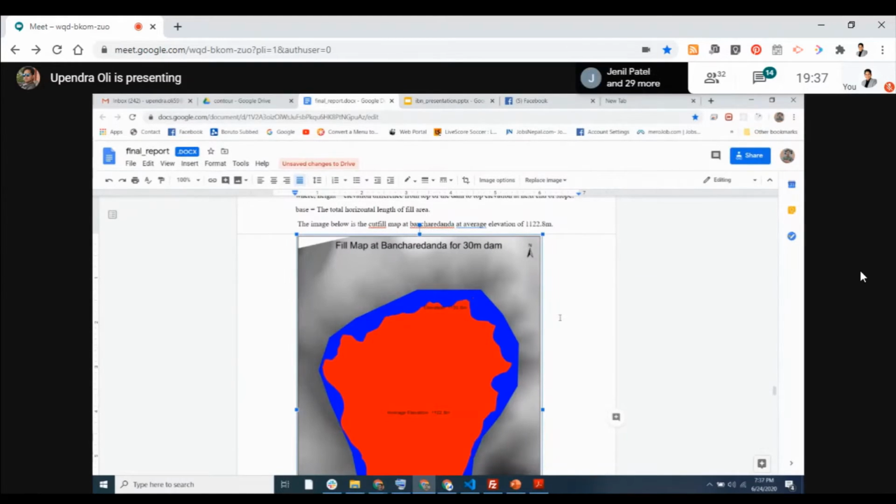But the volume calculated from Pix4D is from the DSM, the digital surface model, which includes the heights of the objects above the ground. That can be trees or grass or a house, anything else above the ground. So we don't want to include the excavation area or the volume of the waste mixed with the grass or trees. So we need to calculate the volume using the DTM, the digital terrain model, which does not include the objects above the ground. There is no functionality to calculate the volume using the DTM, so we did this using ArcGIS.